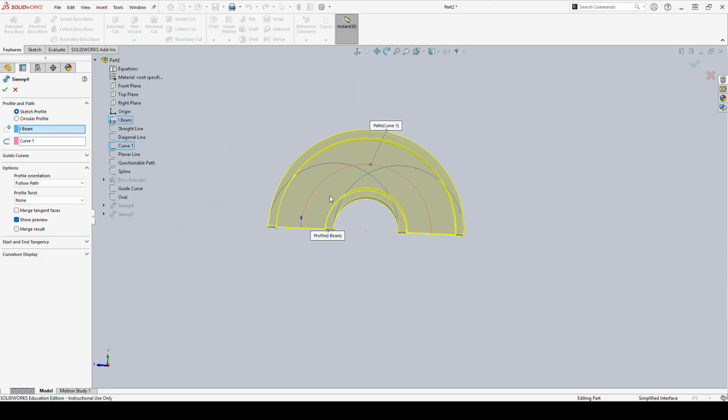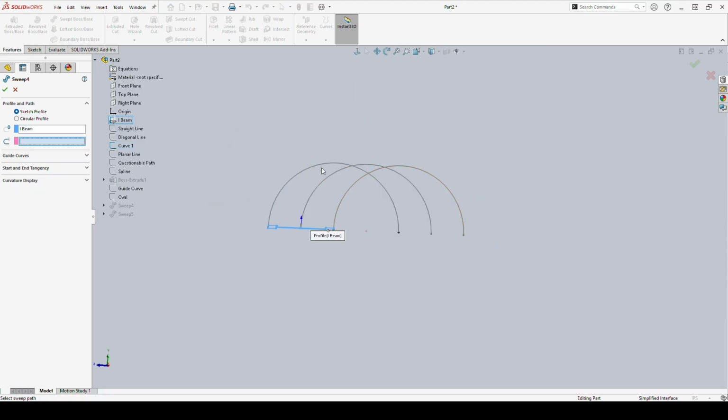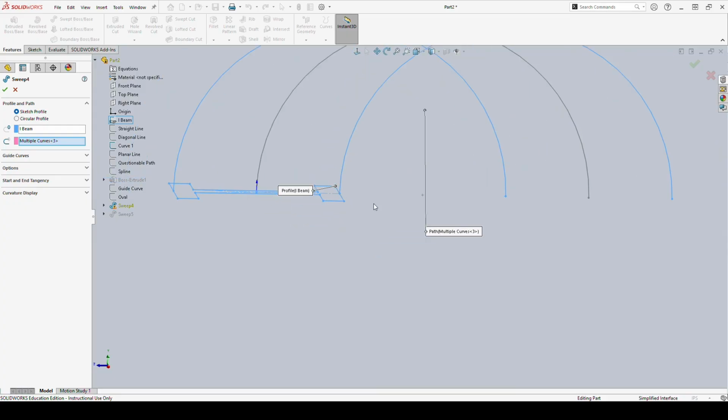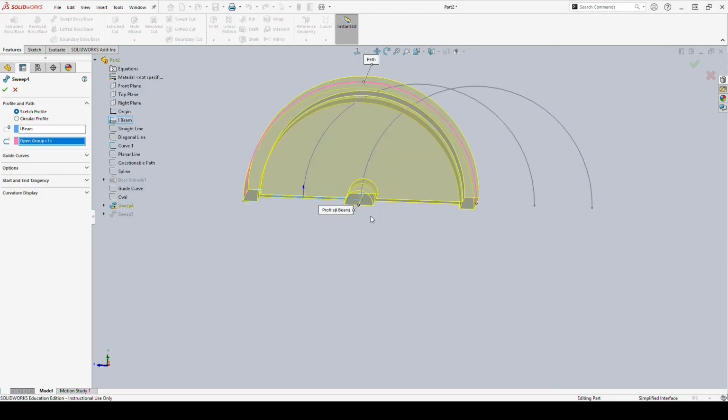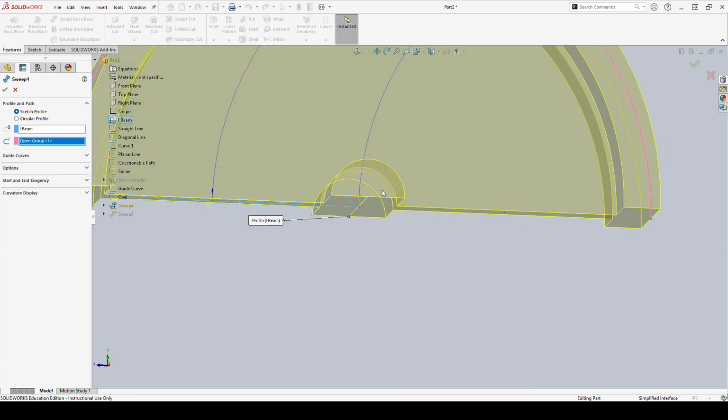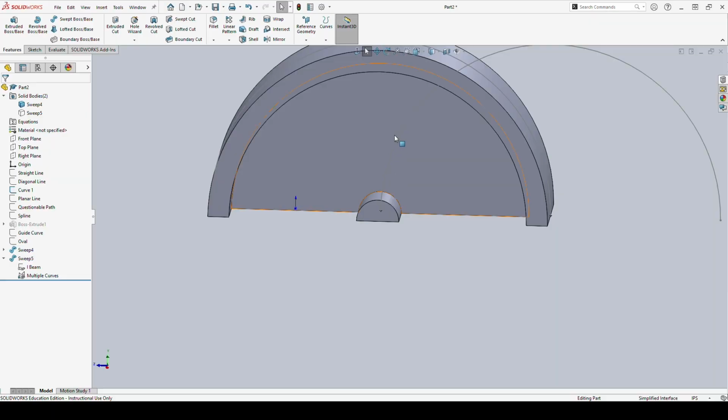And I do this for one more piece. I go ahead and I edit it, and I try to select this outside edge here. But what actually happened is I selected the whole sketch. This is the entire sketch. I didn't see that little box with the check marks, and because I didn't use the check marks, it tried to use the entire sketch, and now I have conflicting two lines, and it can't create it. So what I have to do here is I delete this, and I get my selection manager up, and I can go ahead and follow that path, and it's going to work perfectly fine now. You see that the only pink line is the one that I'm following.